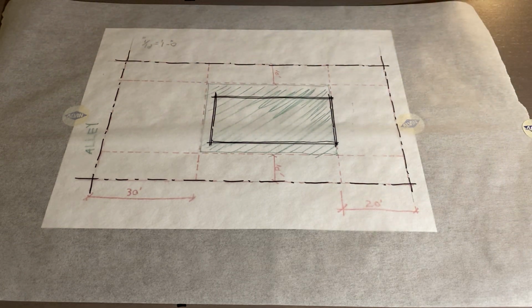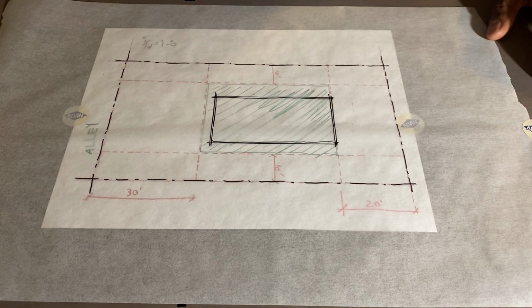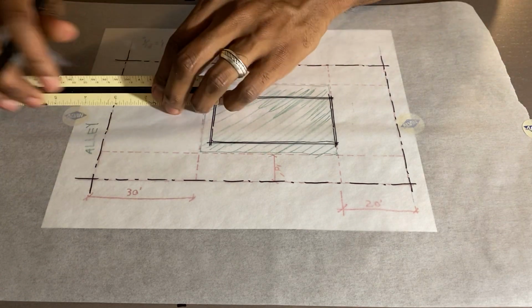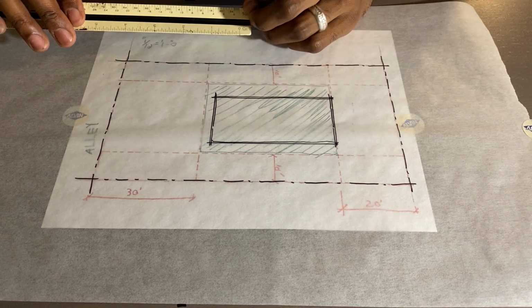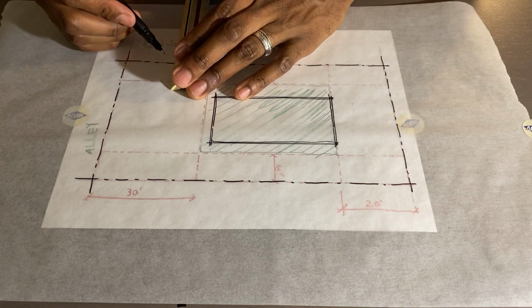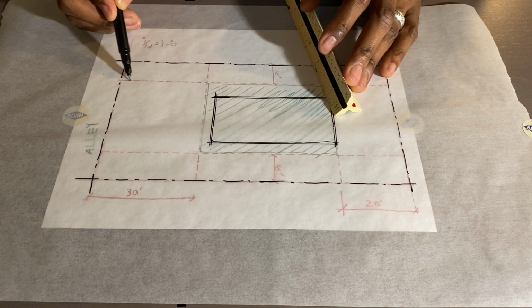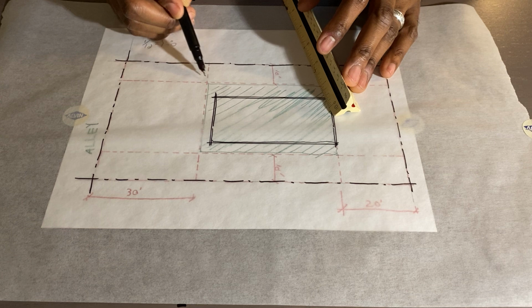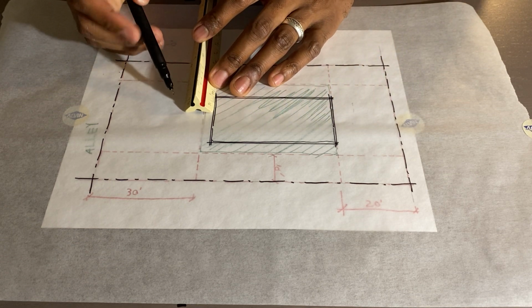So now, per our zoning code, which states that we need 1.5 spaces per unit, I only need three parking spaces now, and not 6. All right, so go through the same process we did last time, and I'm going to try to stay off to one side here. So let's stay here. Actually, let's do this. I'm gonna use my side setback line here as a set aside for how I'm gonna get to my trash lane here. So I'm gonna start here.